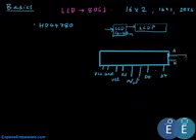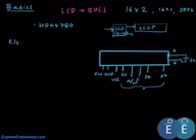What we simply do is connect this to a power supply which is 5 volts, and even this is connected to 5 volts. We'll look at the hardware diagram later. The signals that are used to interface with the controller are these: register select, read write, and the enable pin. These are used along with the data bus D0 to D7 to interface with the microcontroller.